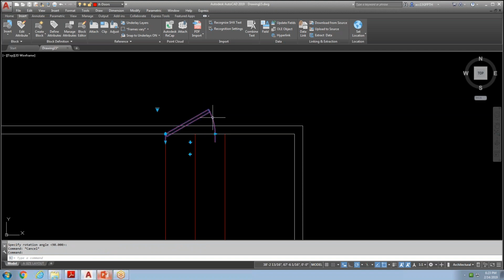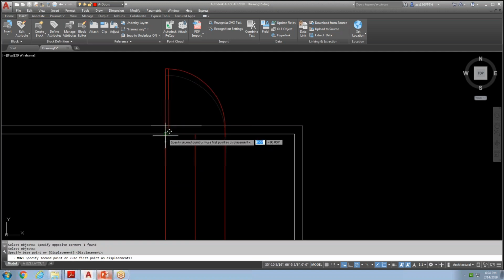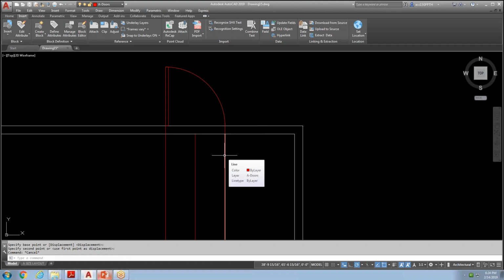Now, this right here, I'm going to go ahead and change it because right now, a couple things. First of all, it needs to be 36 inches. So I'm going to change it to 36 inches, first of all. And then I'm going to change its opening here to open 90. Okay, so I've got that. And so that looks pretty good. Now, the only thing I need to do is I need to move it because right now it's resting on the wrong part. So I'm going to go to here and grab it and grab this and move it right to there. All right. Now, when I do that, that is pretty much how it should be, and that is a proper door.